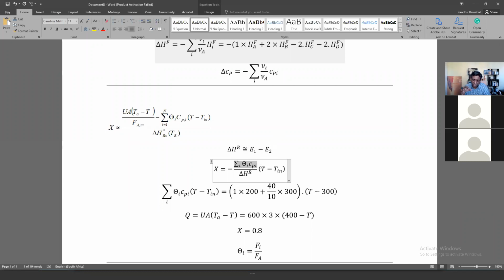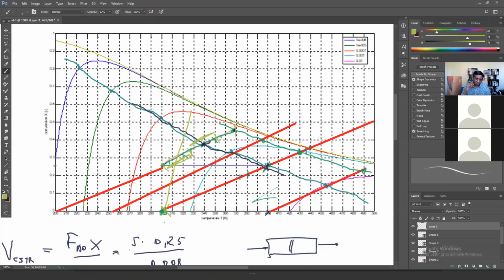So you use a nice high capacity inert, and you can add as much as you like. It's an inert, so it's not going to affect you negatively. Well, except if you're worried about dilution, but let's say it's gas phase, the pressure will go up, then you have safety problems. But anyway, you can change the gradient of that line by adding an inert here.